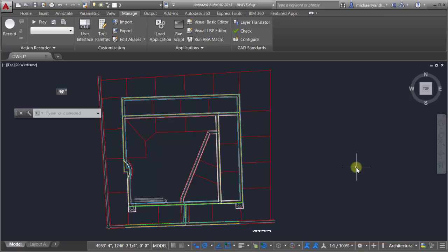Okay, so moving over to scripts, you kind of accomplish the same things, but you can actually do more with scripts. You can run more things. You can batch process scripts across multiple drawings, and it might be a little bit easier just to lay it out instead of having this one long macro string on a toolbar. And also, scripts are easier to share with other people than toolbars.